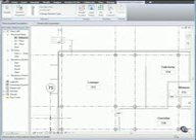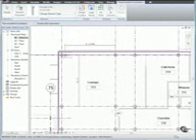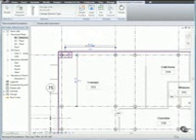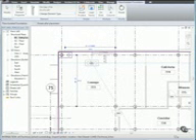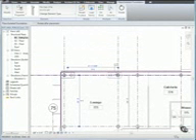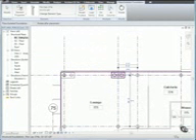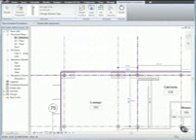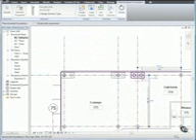Then, in the drawing area, click the column at grid location A1 to place the first isolated foundation. Then, click the columns at grid locations A1.1 and A2 to place additional pile caps. Using the same method, place more pile caps along grid line A.